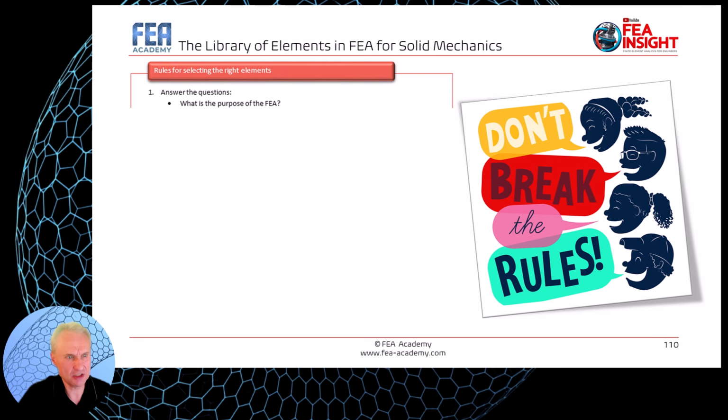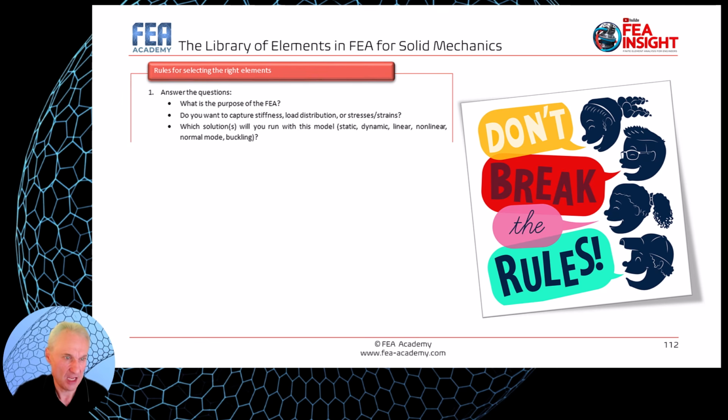First, answer the question: what is the purpose of the FEA? Do you want to capture stiffness, load distribution, or stresses and strains? Which solutions will you run with this model? Static, dynamic, linear, nonlinear, normal mode, buckling, stability? You have to know that before you start, because it will influence the assumptions. Again, it is covered in detail in the Practical Finite Element Analysis course from FEA Academy.